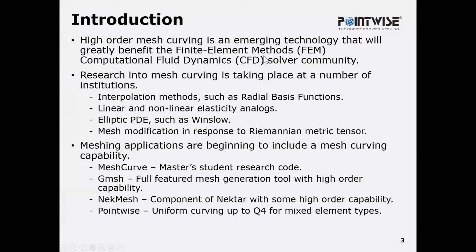So let's just introduce the presentation. The high order mesh curving is still an emerging technology that will greatly benefit the FEA and CFD solver community. The research into mesh curving is taking place at a number of institutions, and they're using different methods. There are interpolation methods such as radial basis functions, also linear and non-linear elasticity methods, elliptic PDEs, and also mesh modification in response to a Riemannian metric tensor.